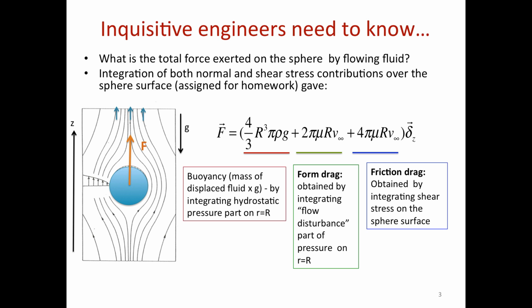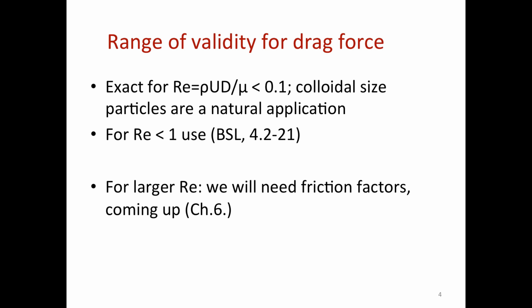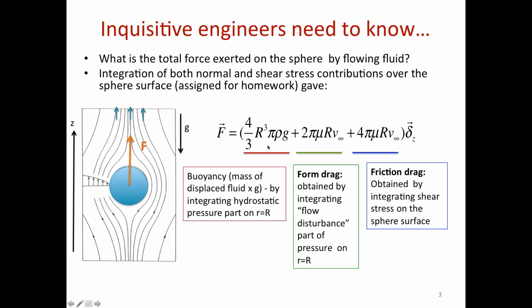So basically, those are all of the contributions to the force, and this portion, 6πμRv∞, which is the combined drag force, we refer to as Stokes formula. Okay, so one thing is, what is the range of validity of this formula?